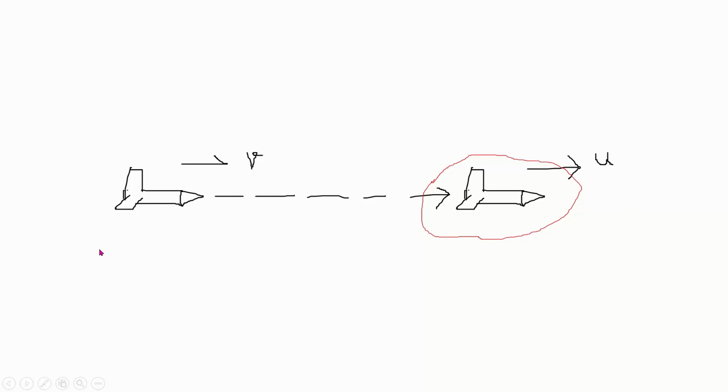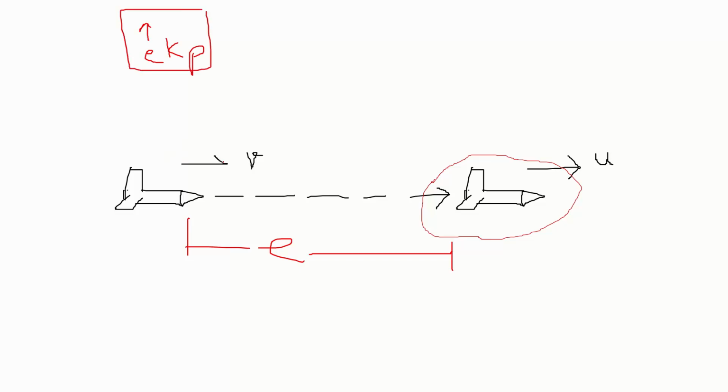Now, this in fact is not possible using an on-off controller, because you will have to continuously follow this particular missile, and for this you will have to generate an error which is proportional to the distance between them. So once the ABM closes in on the target, the error is going to reduce, and the larger the error, the more the proportional controller will cause it to move with a larger velocity towards the targeted missile. So this was given by the expression error times Kp. If you have a larger error, the output from the proportional controller will be large, and the speed v will be large because of the proportional controller.